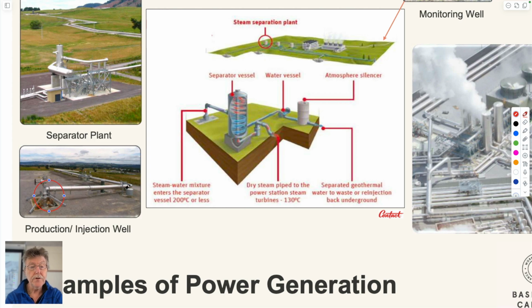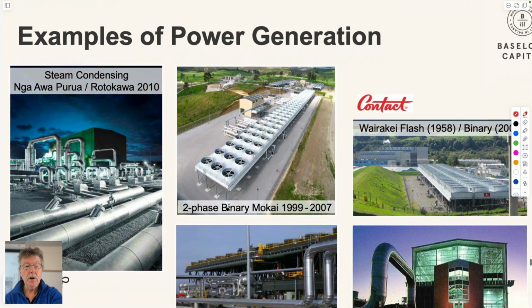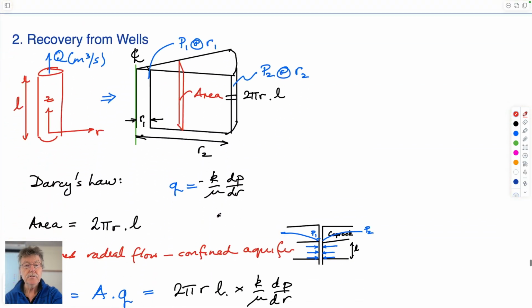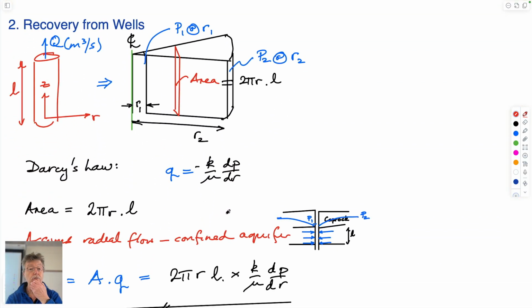They supply water on these pipes. They're typically quite large diameter pipes, 4 to 8 inches perhaps, but they're also insulated and are much larger than the original piping, because you want hot water that you take out of the ground to arrive at the turbine halls hot also.